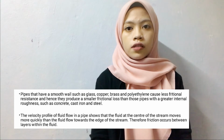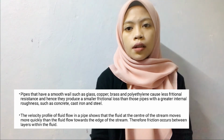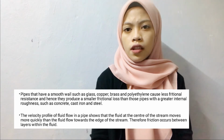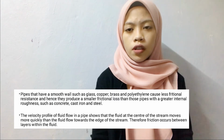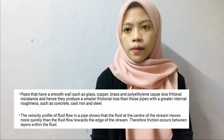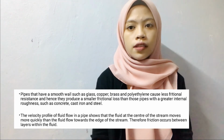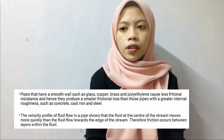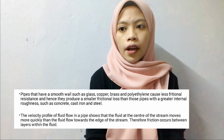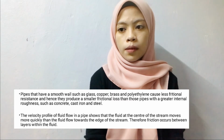Pipes that have a smooth wall such as glass, copper, brass and polyethylene cause less frictional resistance and hence produce a smaller frictional loss than those pipes with a greater internal roughness such as concrete, cast iron and steel. The velocity profile of fluid flow in a pipe shows that the flow at the center of the stream moves more quickly than the fluid flow towards the edge of the stream.